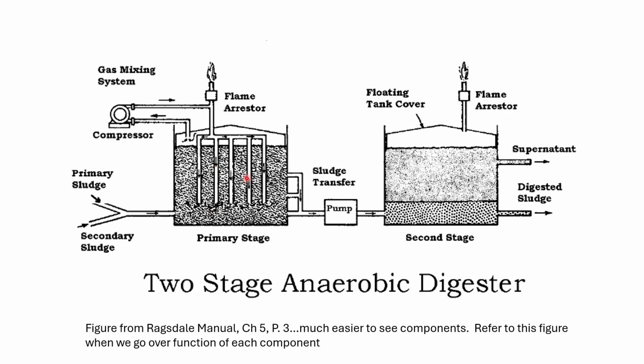And what happens here is we talked about converting the complex organic compounds coming in with the sludge, the protein, sugars, fats, all that stuff. We're converting this in here to the organic acids. We're also starting to form some methane, and that's where that gas is taking off. And we're collecting it up here, mixing it and arresting it at the top of the digester here.